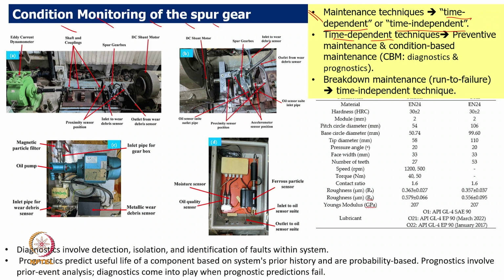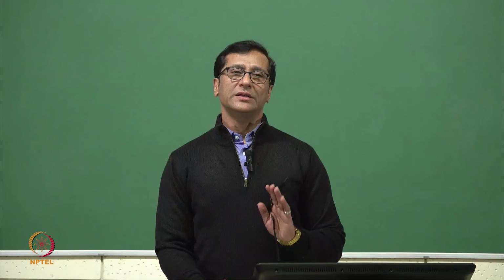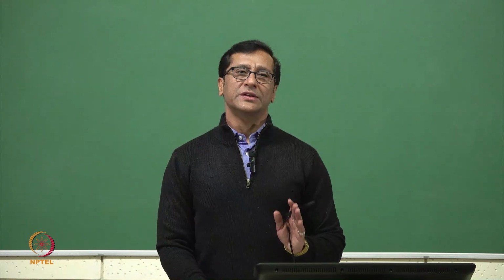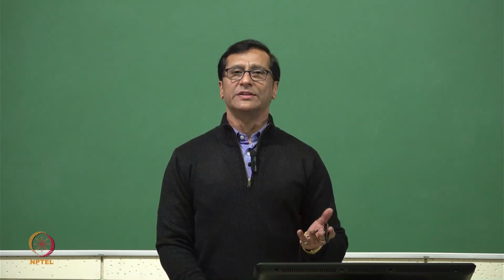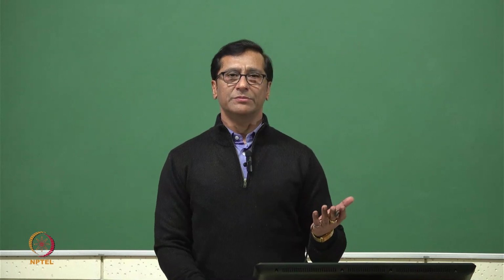Time-dependent techniques are, for example, preventive maintenance after 5 years, or changing the oil after 5,000 kilometers. Another approach is that we keep looking at the condition, and whenever there is a need, we change the oil or the bearing. This is condition-based maintenance. Time-independent is when a component fails and we replace it, and the replacement is not that difficult. It's like a punctured car tire: we replace it with another stepney.